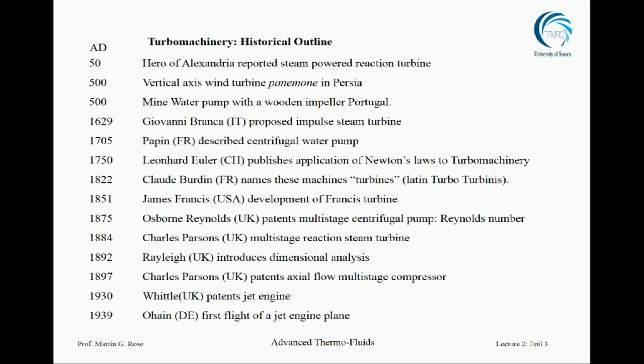So if you have a pump storage scheme where you're putting water up into a lake during the night when nobody wants any electricity, and then in the morning when they all switch their kettles on, you let the water back out of the lake through the Francis turbine and the power comes out. So they're amongst the biggest and most powerful and most efficient machines in the world, are the Francis turbines, so very impressive.